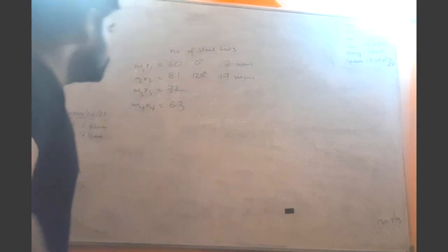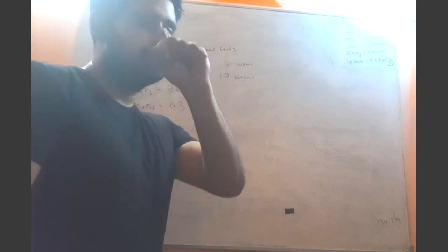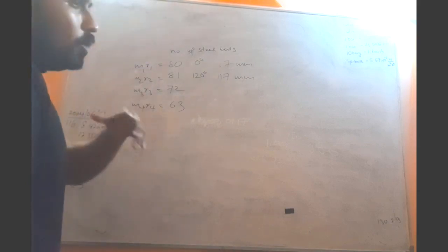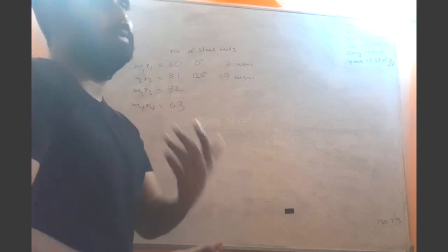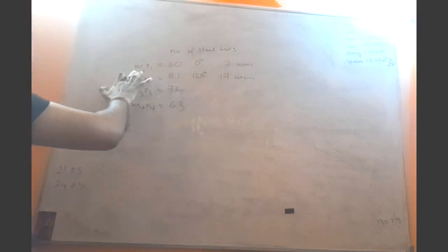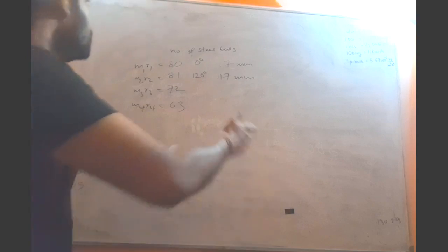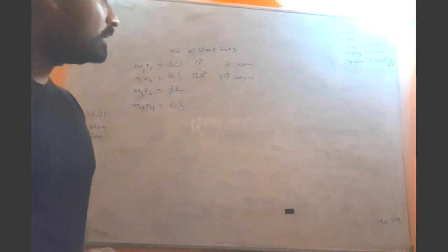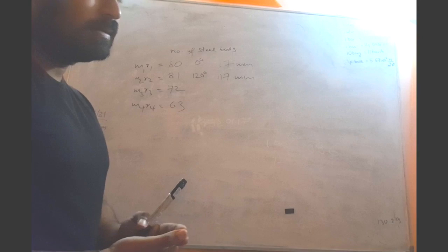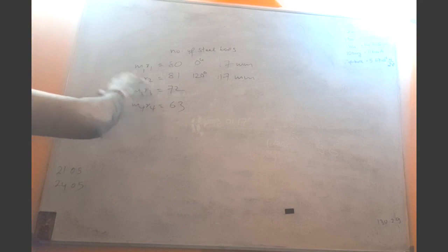Let's see how to sketch the force polygon and the coupled polygon in the balancing of rotating mass experiment. Now we know that we have evaluated the value for the product of mass and the radius of rotation, in terms of the number of steel balls. And also in the experiment, the respective angular positions for the first mass and the second mass.